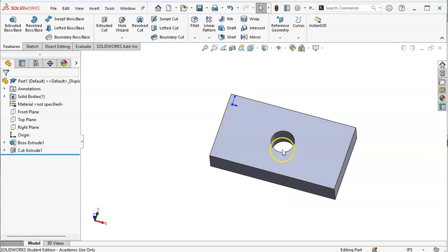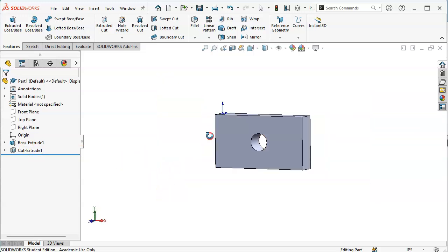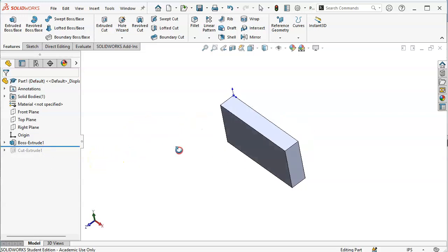There is also the possibility that later on I would want to manipulate this geometry in such a way that I could make changes outside of the original boss extrude and do more what if scenarios by tinkering with that geometry. So just real quick, I'm going to show the rollback. If you ever happen to grab the rollback bar and move it up, notice the hole goes away.